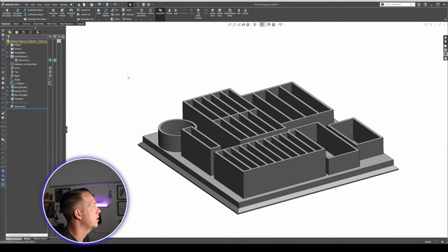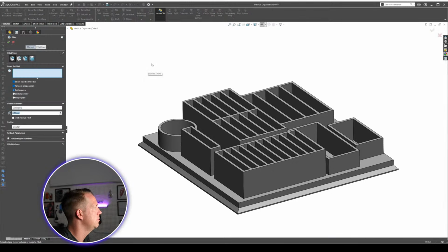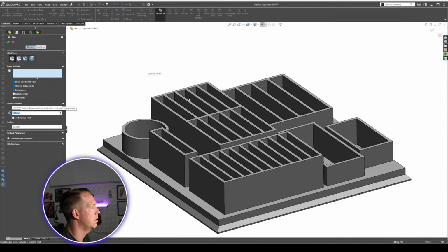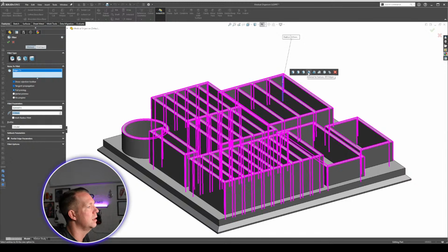And generally that means we're going to add some fillets now. We're going to round off a bunch of things. We've got consistent wall thicknesses. That's great. I want to put some fillets in, particularly the internal corners. So I'm going to grab this edge here, and I've got a 0.5 millimeter radius, and I'm going to go over my fillet pop-up, and I want to do everything internal.